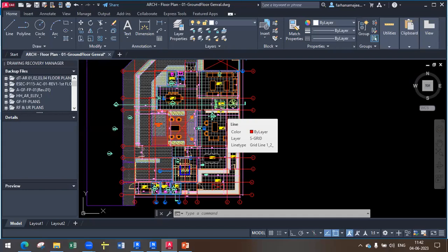In fact, it is not so easy, and it is not so tough either. There is a workflow for how to start a project. First of all, if you are very new to Revit, then you should learn some basic fundamentals, the Revit essential training. Then you should know how to create a proper template in which we have all the elements. Then we should know how to bring an AutoCAD file into Revit, and how to bring the architectural file into MEP services, architectural and structure.